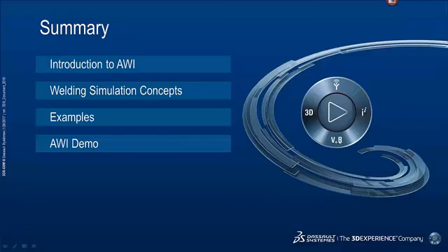Sometimes you make approximations on the energy input. So you take the bead volume and then apply a constant volume flux to the entire bead. It may give you different results compared to implementing the Goldak model directly, but if you're only interested in distortion or other aspects, there are many different methods of simulating this, and that's why we give you the framework so that you can implement your own heat source model.